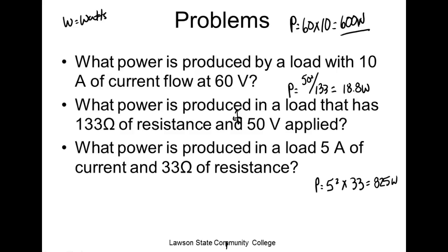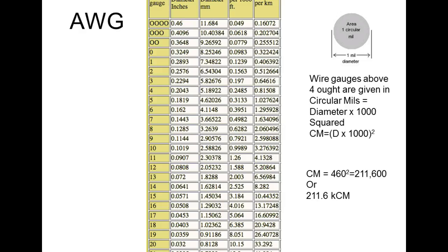And anytime we use these formulas, by the way, they probably won't be on the test that I know of, but later on when we start getting into communication cables, right now we understand that if a wire has an ohm rating and I use the wrong size, so if we go back here and look, if I'm only going a little small distance, this right here, and I'm trying to do 5 amps, I might be able to drop down to a 20 gauge wire because it only has 7/10 of an ohm, right? You understand? So that guy would only be dropping about 1.5 volts over the length of the wire.